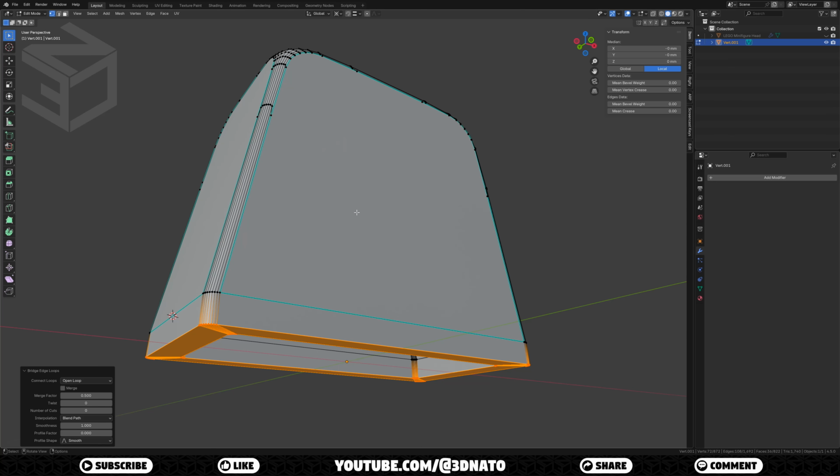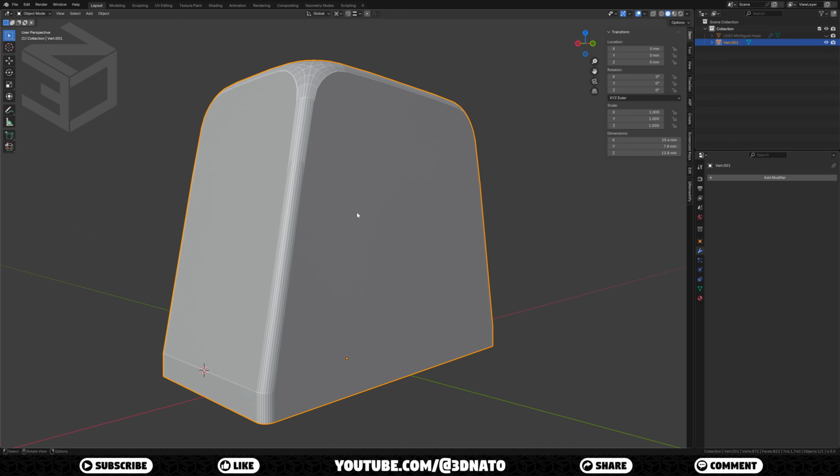To finish this mesh, exit Edit Mode, right mouse and select Shade Auto Smooth. Now press F2 to rename and rename it Torso. The base mesh for the torso is complete. Now I'll create a series of Boolean meshes, first the ones to add and then the ones to subtract.